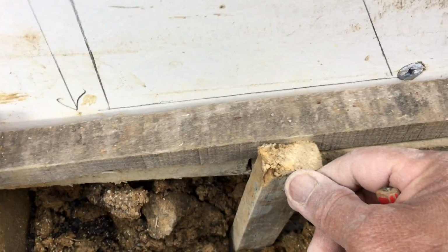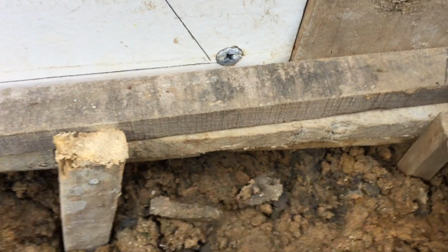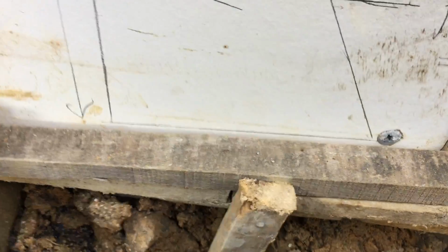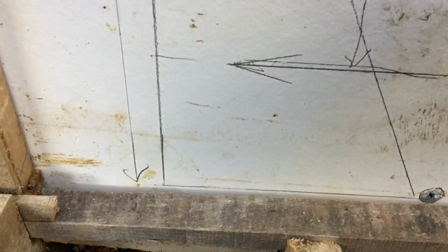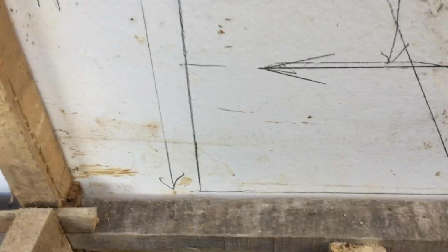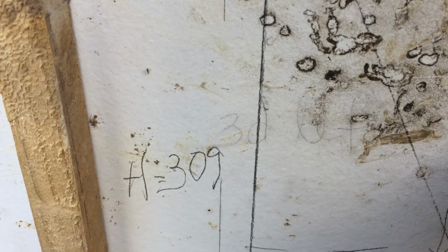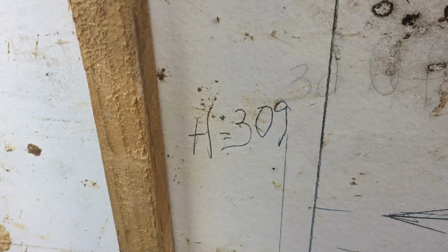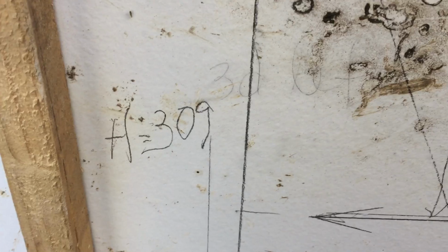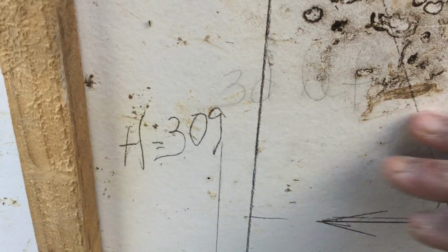That's why, as you can see, I put some protection here, pegs here, so that I can resist the force induced by the concrete inside the formworks. The maximum pressure is in here, so I put nails in here to resist the pressure of fresh concrete on this area.